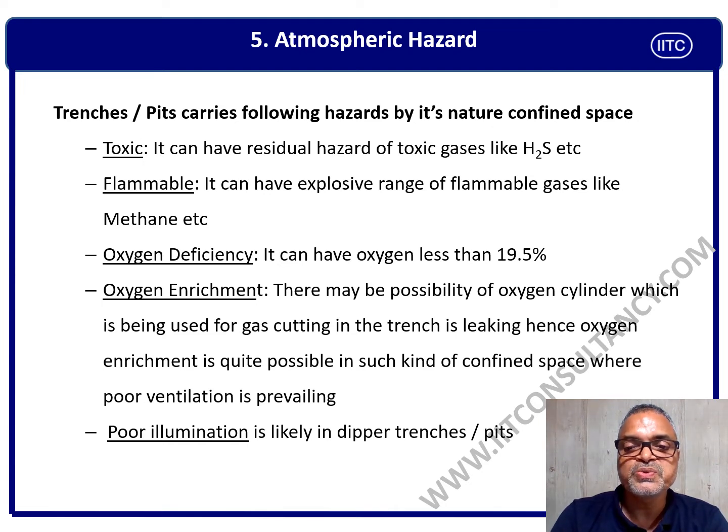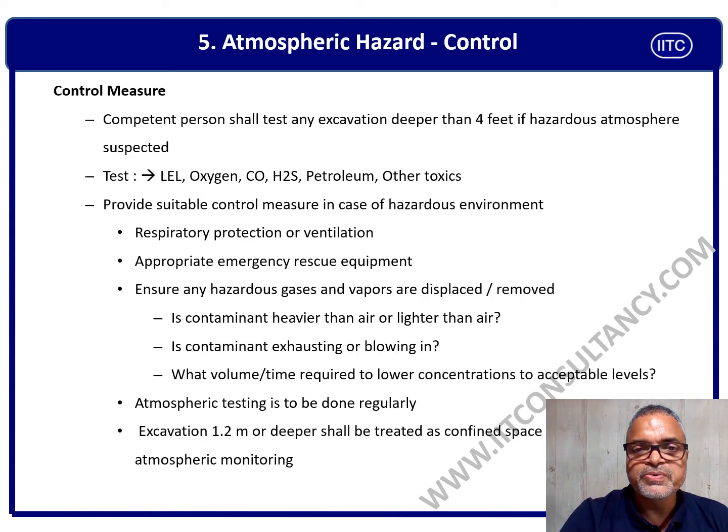So we need a permit to work system when we are going to enter the excavation site again after the next shift. And poor illumination and poor ventilation are also among the atmospheric hazards for excavation safety. Now we are going to see atmospheric hazard control.